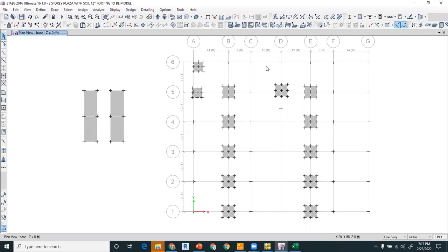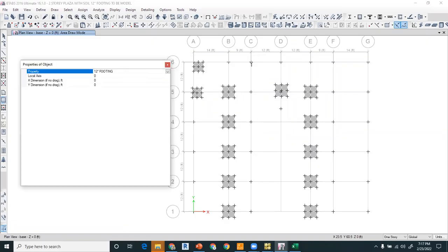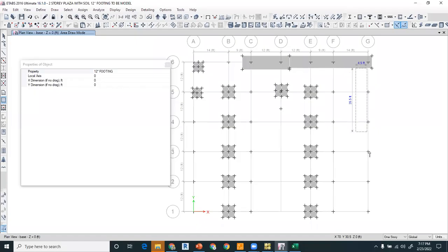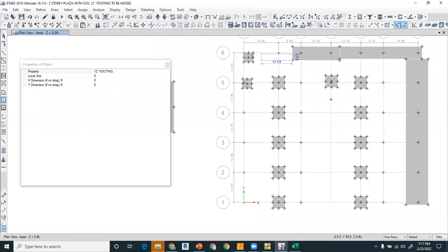आपने ये क्वेश्चन पूछा था कि स्ट्रिप फुटिंग और वॉल फुटिंग में क्या फर्क है? स्ट्रिप फुटिंग और कंबाइन फुटिंग। देखिए, फॉर एग्जांपल आपके पास ये दो कॉलम्स हैं। अगर मैं इन दोनों कॉलम को इस तरह की फुटिंग प्रोवाइड कर दूँ, दिस इज कॉल्ड द कंबाइंड फुटिंग। लेकिन अगर मैं इन दोनों की फुटिंग भी इस तरह लेकर जाऊं और इन सारे कंबाइंड फुटिंग को कंबाइन करके एक ही कंसिडर करके डिजाइन कर लूँ, सो इट विल बिकम स्ट्रिप फुटिंग.